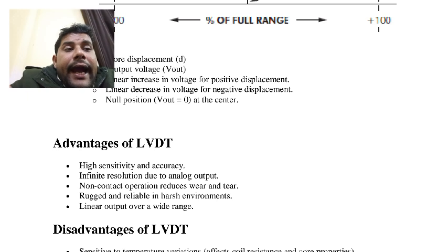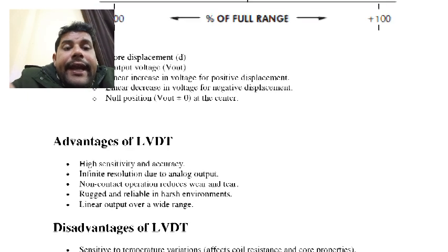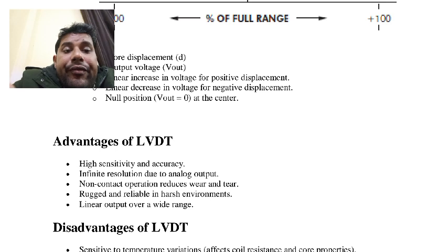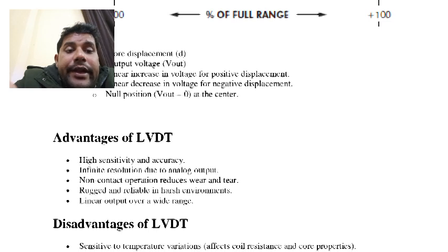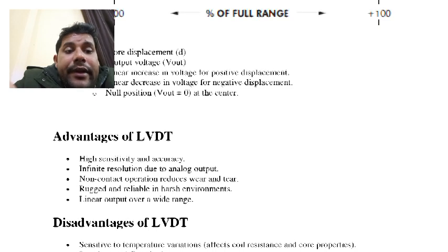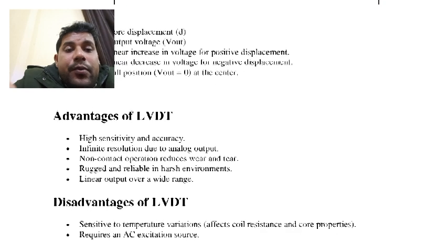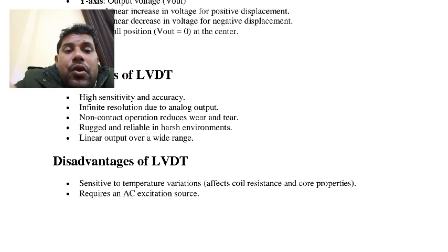Advantages of the LVDT: high sensitivity and accuracy, infinite resolution due to analog output, non-contact operation so no wear and tear, rugged and reliable, linear output and wide range.